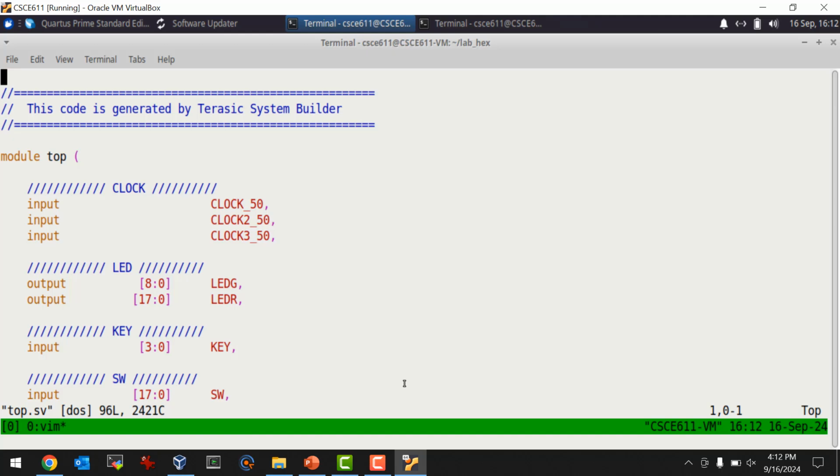You can see those here. So I've got 18 reds and there's actually 8 greens here, and then there's a green up here in the middle of the hex displays. And then there's the hex displays, so there's 56 bits there because there's 8 hex displays and each one is 7 bits. Unfortunately, we don't have access to the decimal point. We just have the 7 segments.